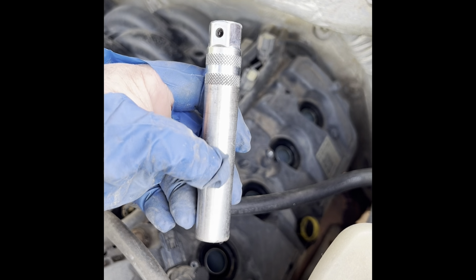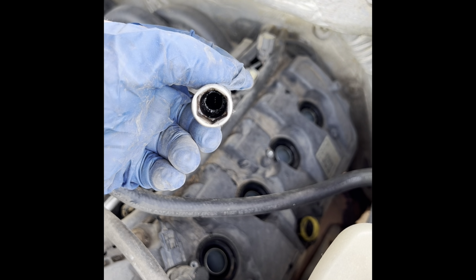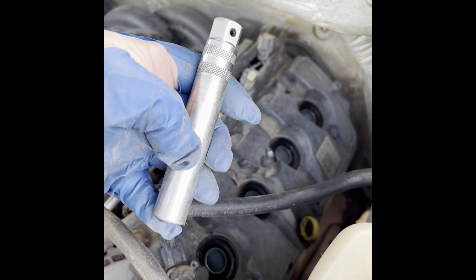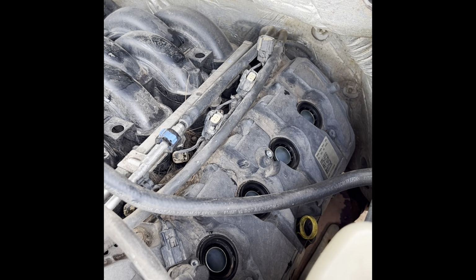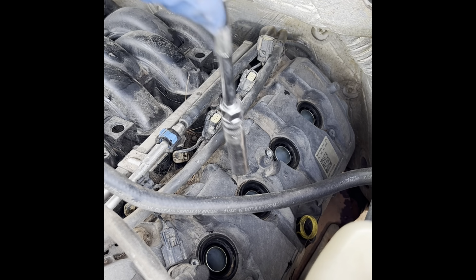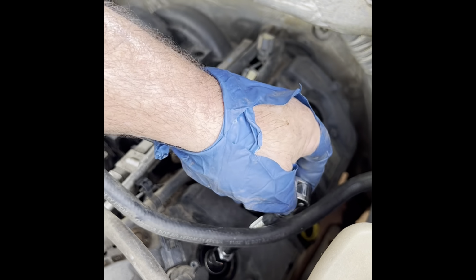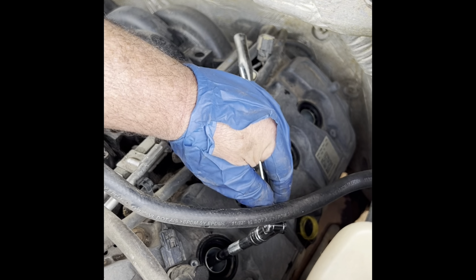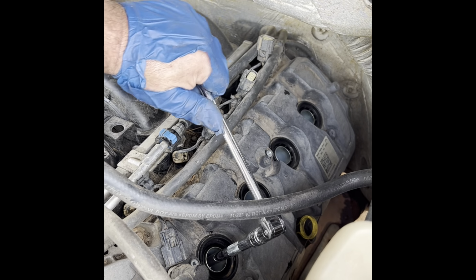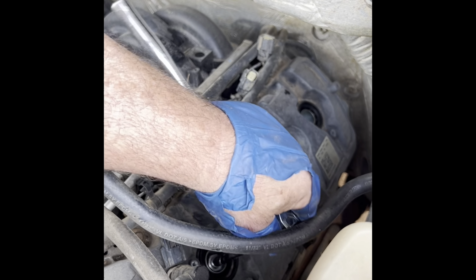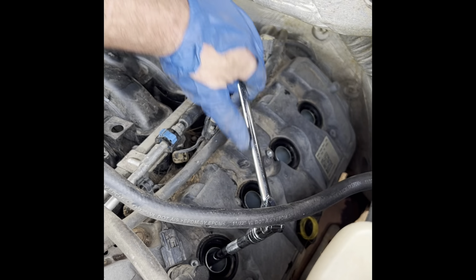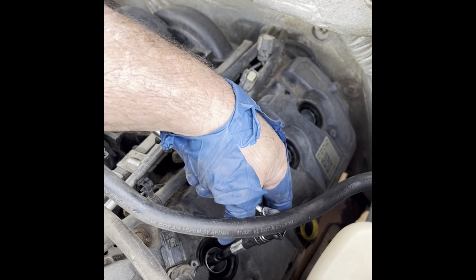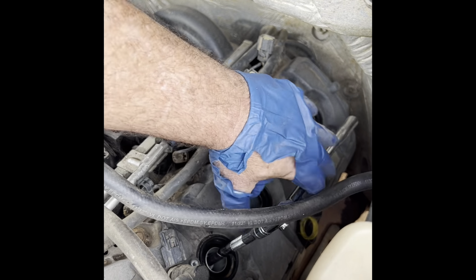Next, I'm going to take this long 5/8 spark plug socket. You can pick these up. I think this one's even probably a Harbor Freight Taiwanese. You can pick them up anywhere for 10 bucks or so. But you're going to have to have them if you're working on these Fords where the spark plug's way down in the head. It takes all that spark plug. I have done it with the shorter sockets, but it is not fun. If your socket comes off your extension down in the hole, then you have to go hunting for your magnet and all that.